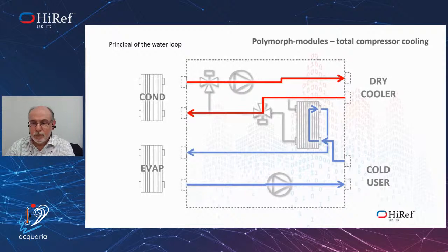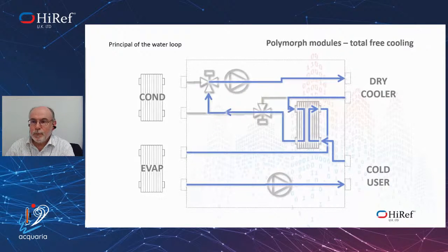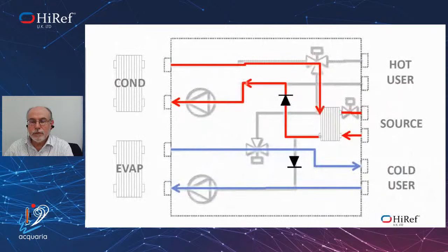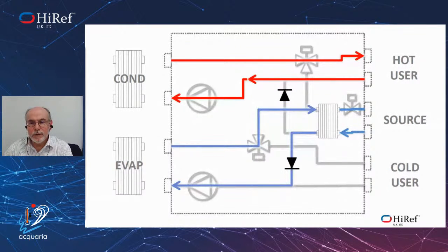If you've got a 2-pipe system, it complicates the way the pipework operates because of how you're transposing water around. And then, of course, you can go to the 6-pipe unit, and then it's easier using a standard chiller, because you're rejecting heat, you're putting out cold water, and you've got hot water at the same time, and it's moving that water around to enable you to utilize where it's going.